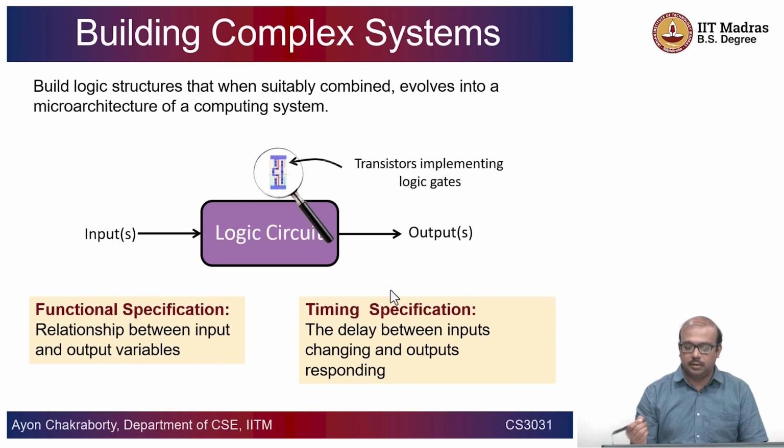But just to give you an introductory understanding, we are going to deal with binary variables, or logical or Boolean variables, and logic gates help you implement the Boolean functionalities at the hardware level. For example, if I have an AND operation, I mention that as A dot B as a Boolean algebra construct, but you can also have the similar thing implemented on hardware using a gate circuit, which could be an AND gate circuit or an OR gate circuit and so on. So all the Boolean algebra expressions could be implemented in hardware using these gates, and those are implemented using a network of transistors.